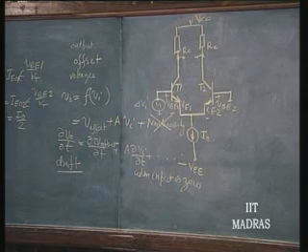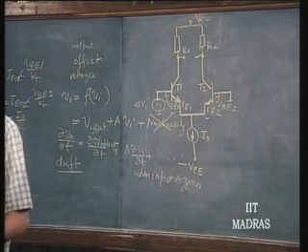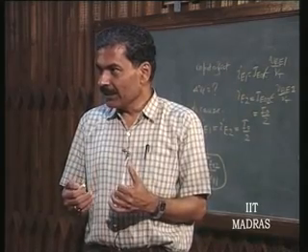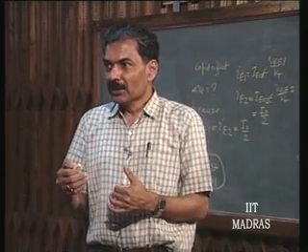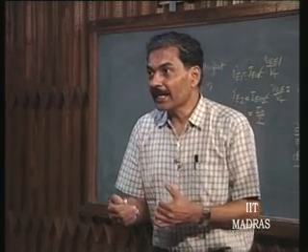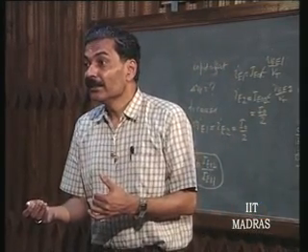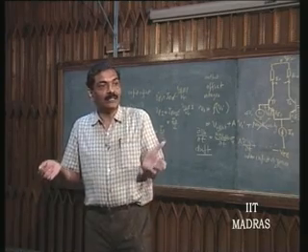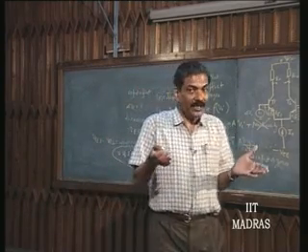Why do you use Darlington pairs? You want to improve the input impedance of the input stage, then you might go for Darlington pairs. So when the input impedance is increased, automatically you are sacrificing input offset. This is the practical situation that exists.